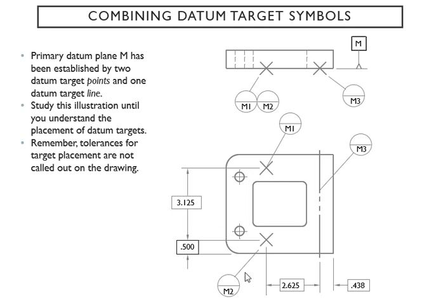Of course, here are your basic dimensions right there, which when you spot them, you can trace all the way to the datum target points right there. Make sure you study this until you know where they are, so you can quickly locate them. And here also are basic dimensions. If you go along that, you're going to find your datum target line.